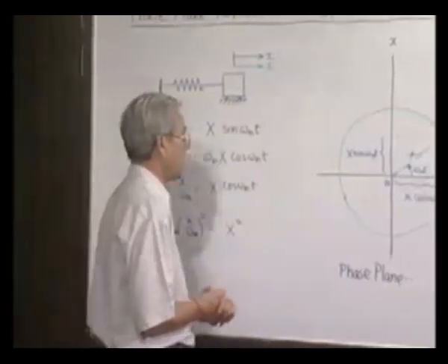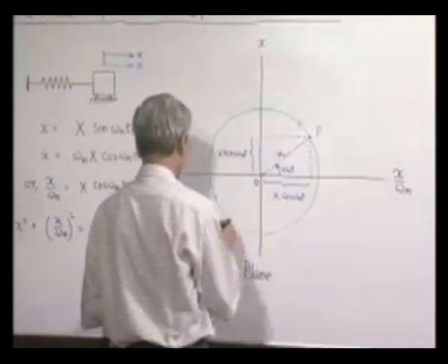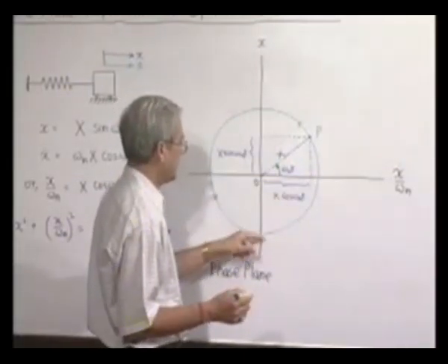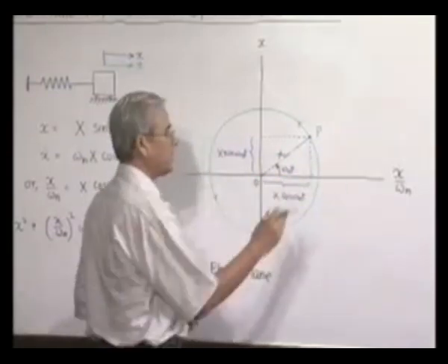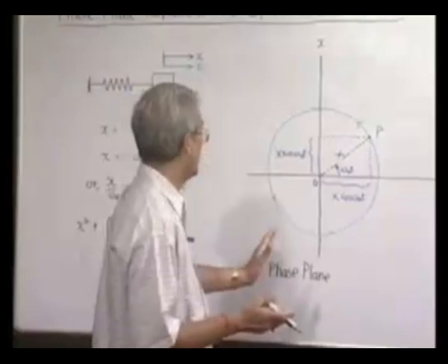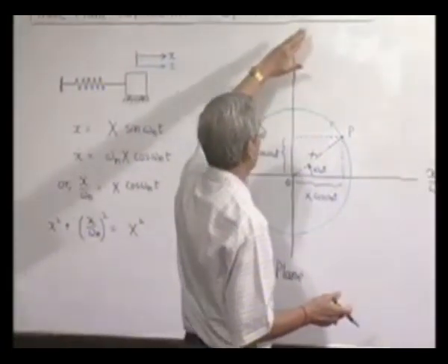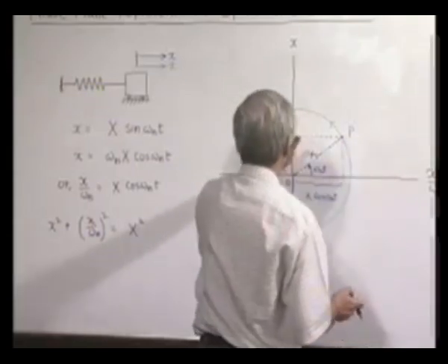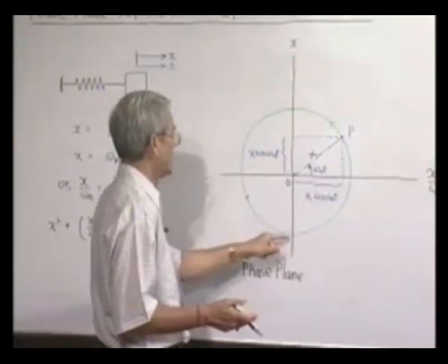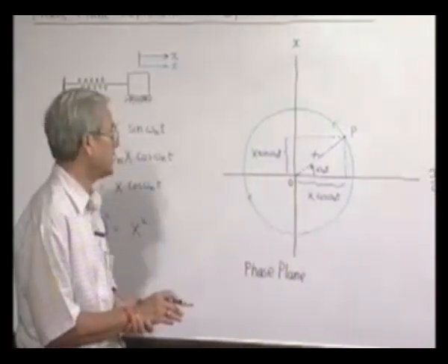and one thing should not be forgotten, that means there is an arrow. This arrow has to be in this way, because when velocity is in the positive quadrant, this means here, so when velocity is positive, x dot is positive, algebraically x must increase. So during this half cycle x is increasing because velocity is positive. On this side where velocity is negative, x is decreasing from this value to this. That's why the arrowheads are unique and it must be represented like this.